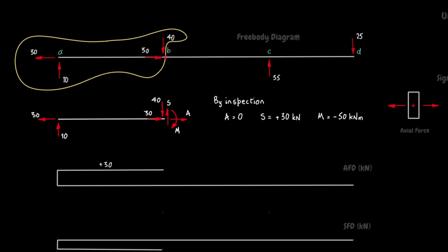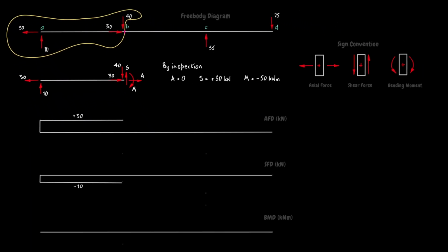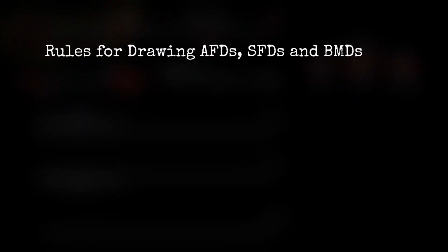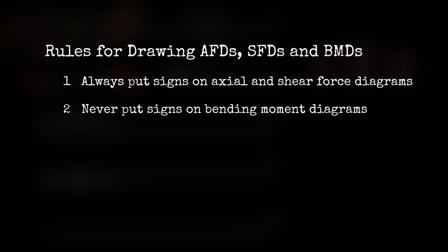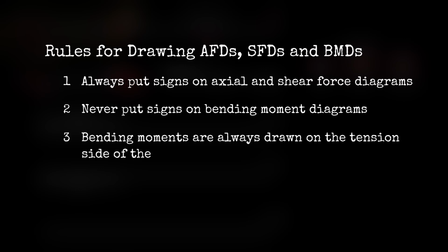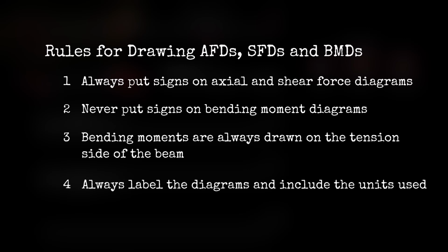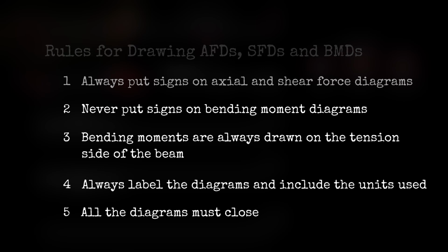Before plotting the results, now is a good time to remind you of Dr. Jim's rules for drawing axial force, shear force and bending moment diagrams. 1. Always put signs on axial force and shear force diagrams. 2. Never put signs on bending moment diagrams. 3. Bending moments are always drawn on the tension side of the beam. 4. Always label the diagrams and include the units used. 5. All the diagrams must close to satisfy equilibrium.